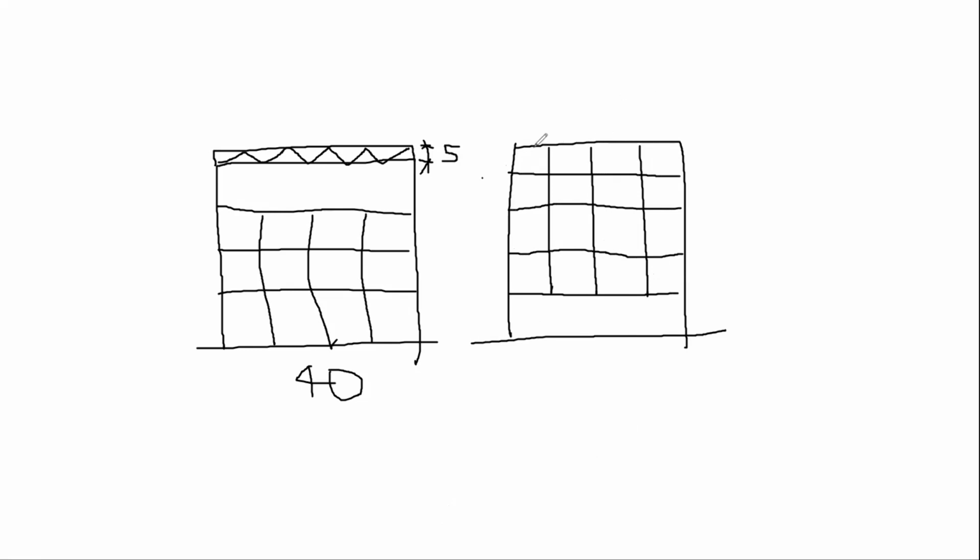First of all, the roof structure is very shallow. This is 8 meters, and so we divide that by 8. So the depth of this is only about 1 meter. And this is the problem, because we've got this wide span here. So we've got two problems.